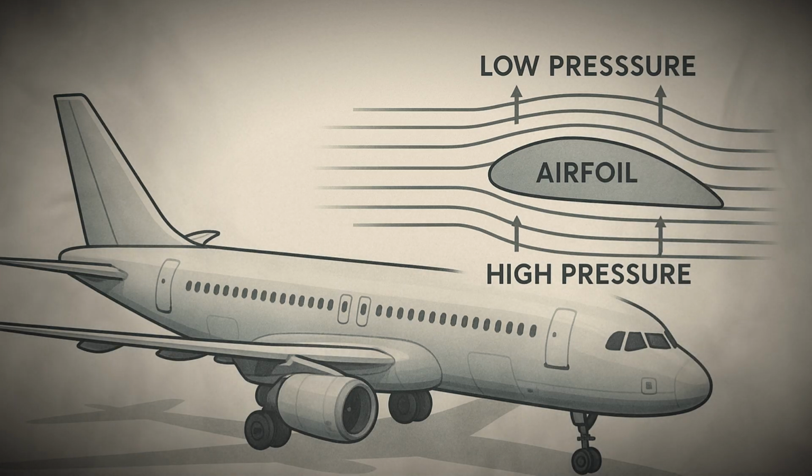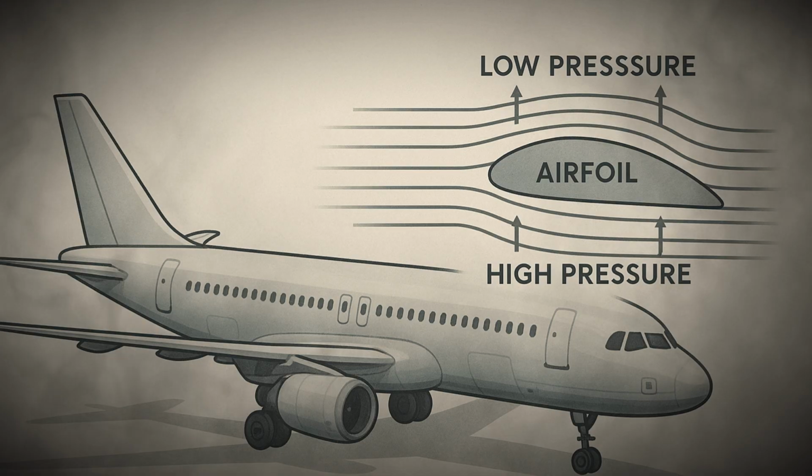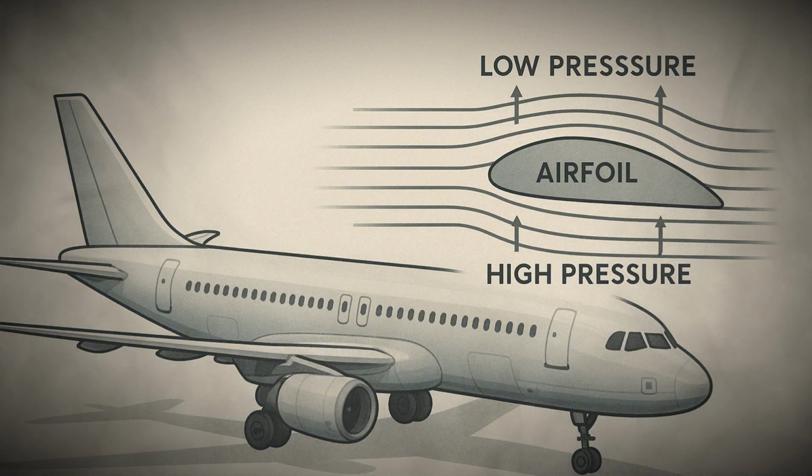ailerons and flaps. Ailerons are movable sections near the wingtips that allow the airplane to roll left or right by increasing lift on one wing and decreasing it on the other, while flaps are located closer to the fuselage and can be extended downward to increase lift during takeoff and landing. Some wings also contain spoilers, which can disrupt airflow to reduce lift and increase drag, helping the aircraft descend or slow down after landing. The structural integrity of the wing is another vital factor.